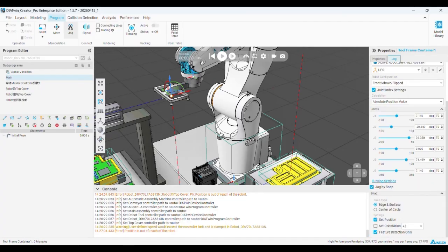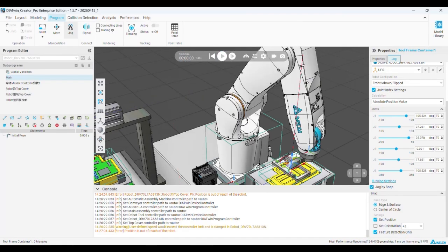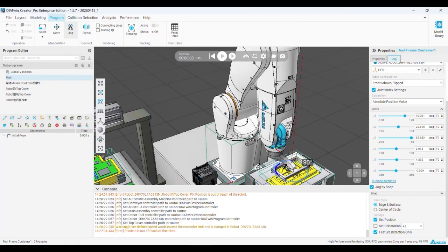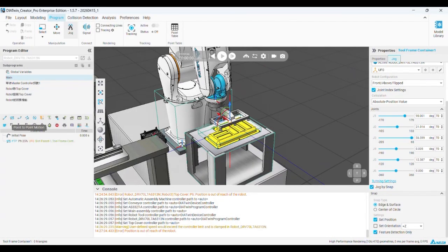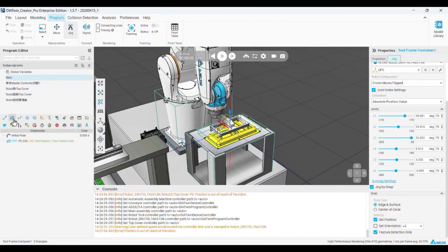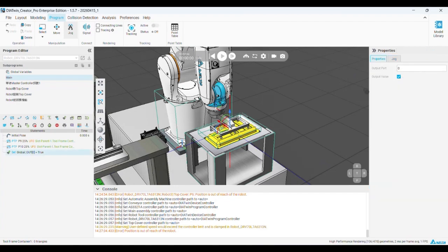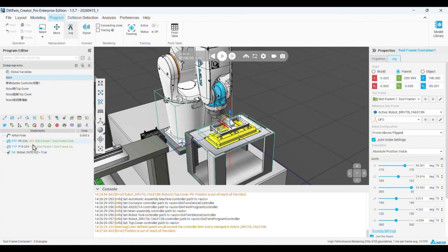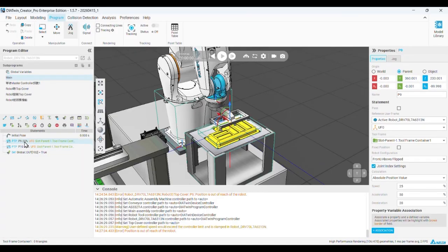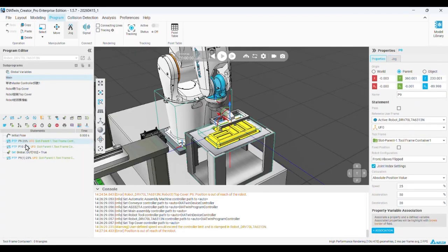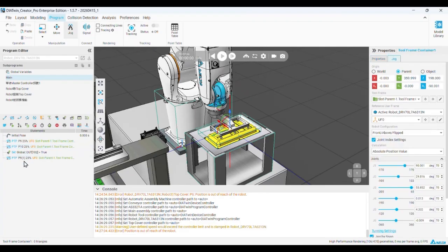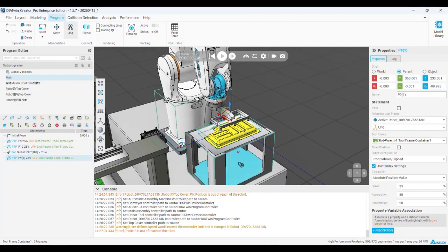Okay, with this, if you just select this, now you can just hit the point right here. And then maybe change the directions. Then make a ready point, a teaching point, add a receiver, add a DO statement. The port is 102. Maybe we can use copy and paste, it's also fine. So there will be a ready point, teaching point, and ready point again.